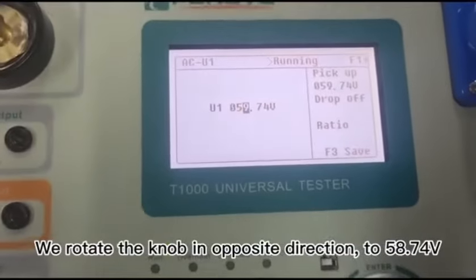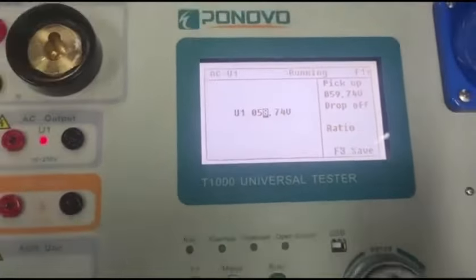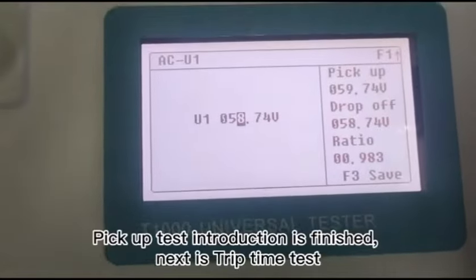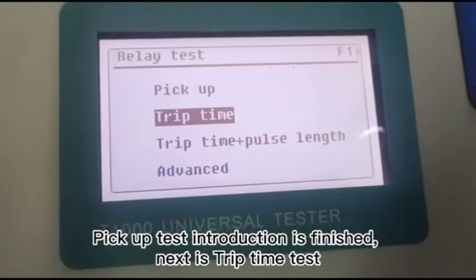We rotate the knob in opposite direction, to 58.74 volts. Then we open the binary input, the drop-off value and ratio come. Pickup test introduction is finished. Next is trip time test.